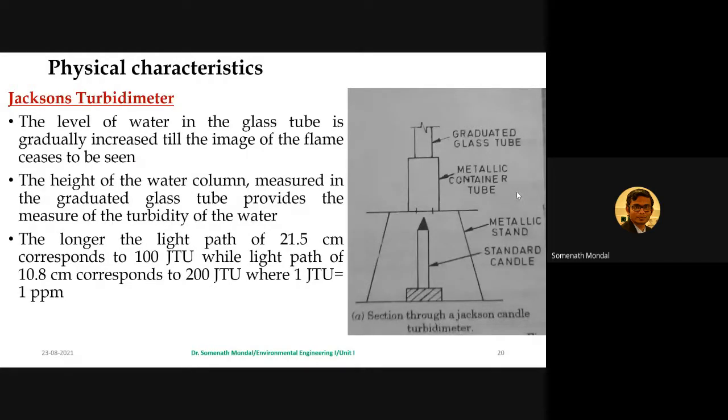Fine. So you can gauge that if you are able to see a longer light path, that means the turbidity is lesser. That part is also important to remember over here. So we have the Jackson turbidity unit also, like what we see as the nephelometric turbidity unit.